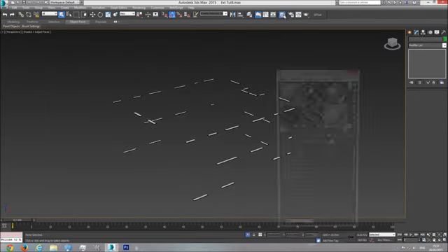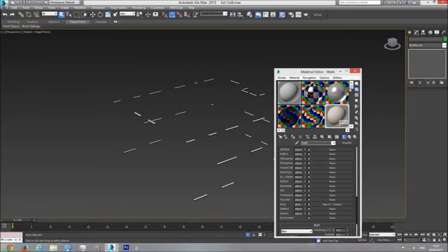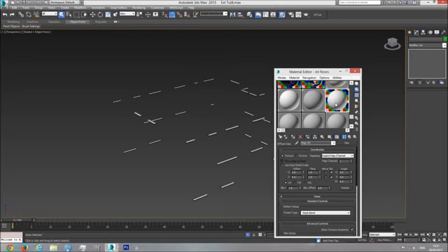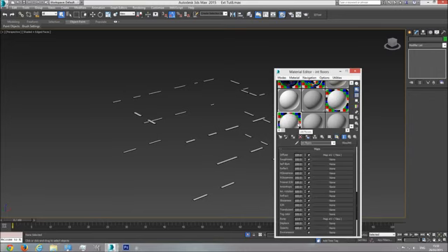Let's give them a material. I want to give them a material like the floor inside of the house, but without the separations. So I'm going to copy this interior floor material here, drag, and I'm going to call it ledges. They're going to be white.